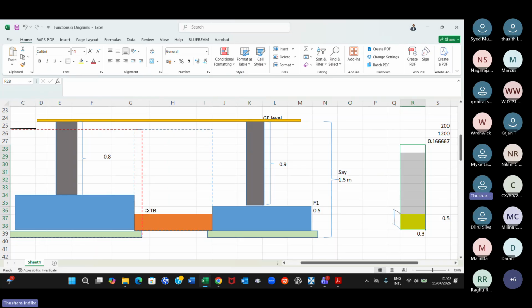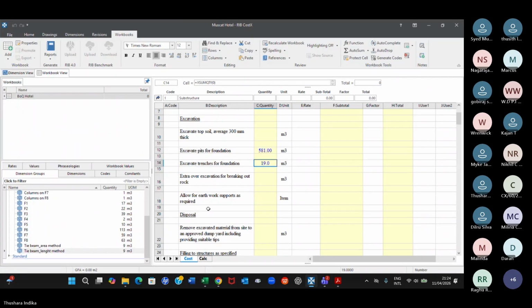But during the preparation of the BOQ, okay? But during the post-contract stage, of course, you need to deduct these quantities and get the actual value. In the estimation purposes or BOQ preparation purposes, you can measure to the higher side. I think it's clear, right?